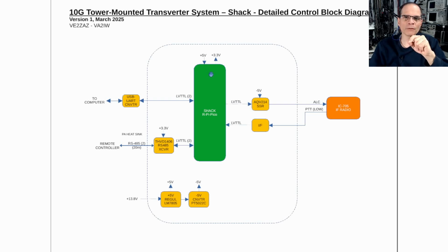The reason is I want to reserve the onboard USB connector to reprogram the Raspberry Pi Pico when necessary and segregate the communications onto a separate UART and separate communication channel. So that's the communication with the PC. On the other side, facing the tower and the remote controller, I am using RS485. It's one single twisted pair, so it's a simplex system I've decided to use, one message at a time, so a single pair of wires will allow me to communicate in both directions.